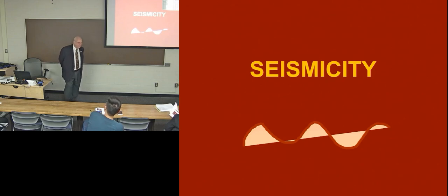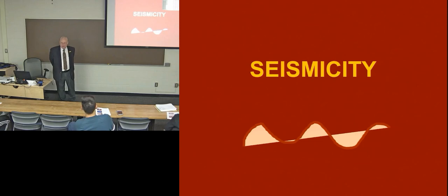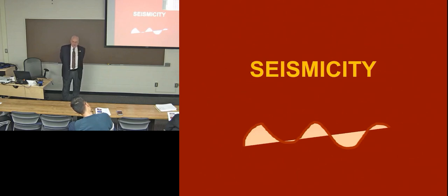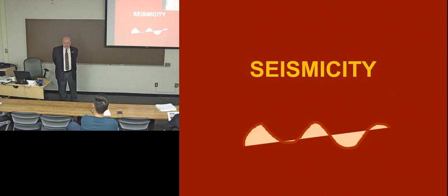Well, at that point in the early 70s, we had Professors Streeter and Wiley in hydraulics here at Michigan, and they were developing a mathematical technique, a finite difference approach, called the method of characteristics. And so they used the method of characteristics to predict what the first mode natural frequency was going to be.